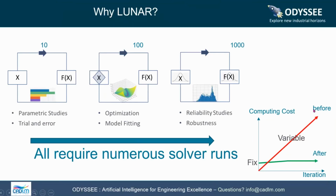So what we think is that there is a way of doing this differently. If we spend a little time and money at the beginning, an amount which is fixed, we can exploit that to build a model, which we call a real-time model or a reduced order model. As the number of iterations goes up, that cost doesn't change, or it changes very little. This is a huge advantage, whereas if I wanted to do traditional direct iteration or even response surfaces, the cost goes up linearly.